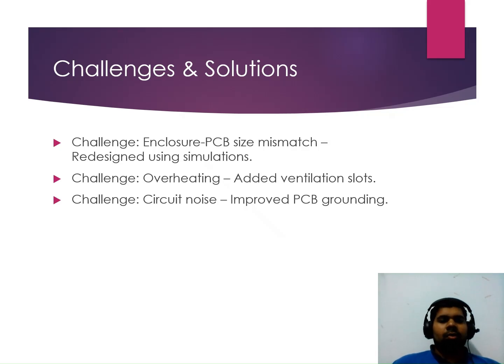For challenges and solutions, the first challenge was that our product's PCB had a size mismatch, so we redesigned it using a simulation. The second challenge was overheating, so we added more ventilation slots near the components. The third challenge was circuit noise, so we improved it with PCB grounding.